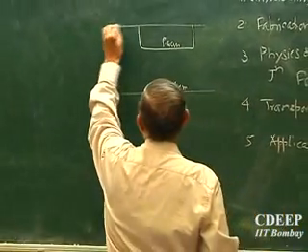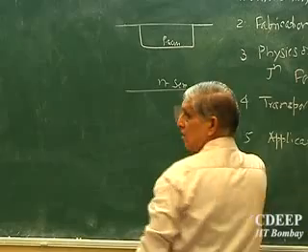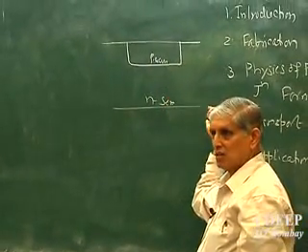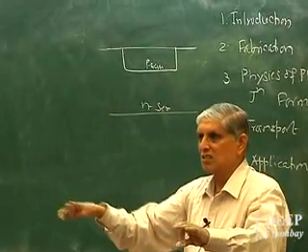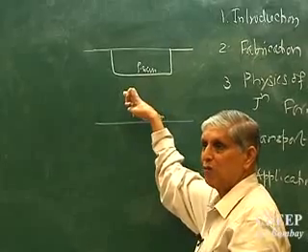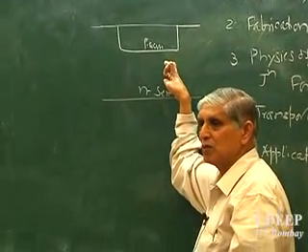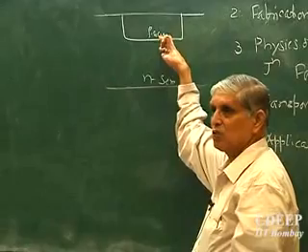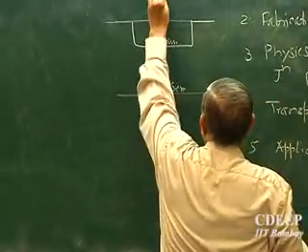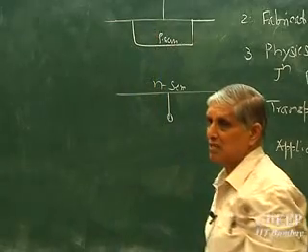So I don't want the rest of the areas to have impurities introduced. Is that point clear? The wafer may be any size, the chip size may be even smaller. Each chip of a diode, I want selective area p diffusion. Is that correct? This will act like a diode. Then one contact here and one contact here will make a diode.